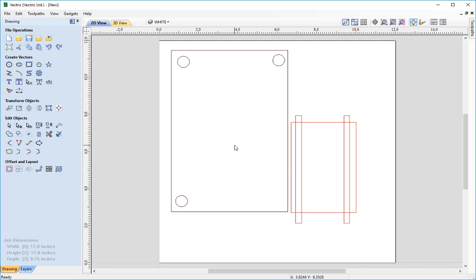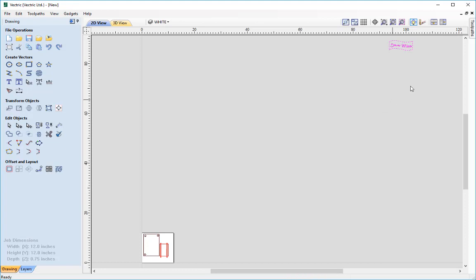they are. Now the first option would be to zoom to fit. So this basically zooms to fit all the vectors inside our 2D view work area. Now we can find that icon underneath the view toolbar here, and this icon says zoom active view to the draw limits. Now simply click that, and you'll notice that our imported vector is actually in the top right, very far away from our XY 00 origin. And basically this has happened because the vectors here that we've imported have been saved that far away from the X0, Y0, and that's not in our 2D work area.